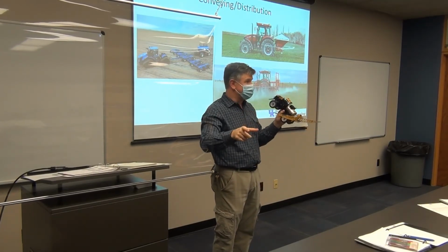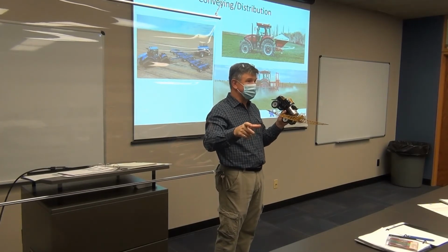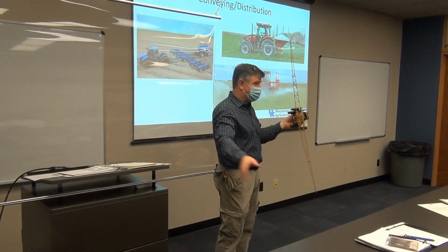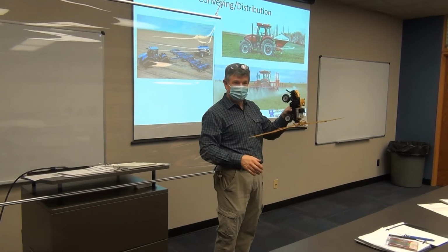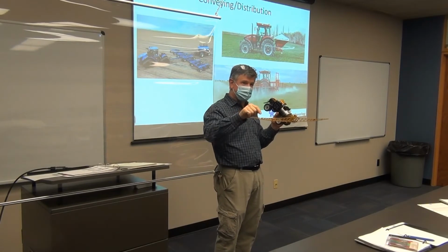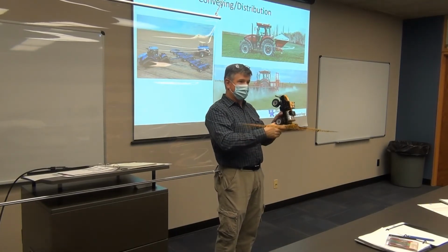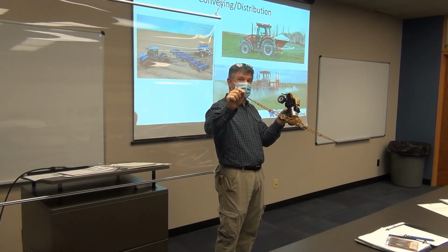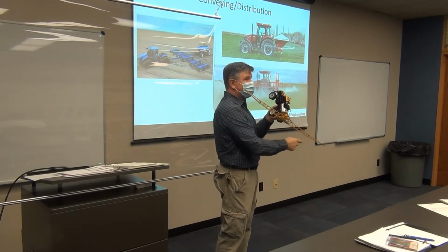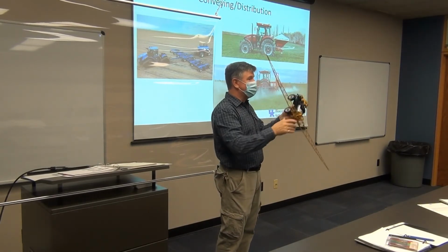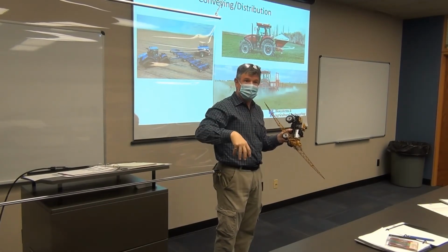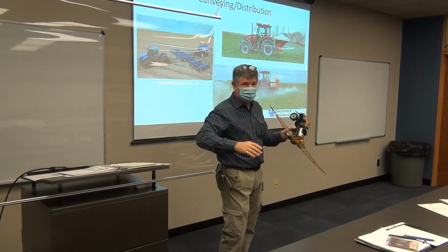What's that doing to my application rate on the ground out here? Wow, it's changing it, right? In fact, when I turn real short, I can actually make this boom go backwards, and I can spray back and forth and double and triple cover stuff as I wiggle around tight corners. But now if I'm injecting the chemical at each one of these nozzles out here, when I start around the corner, I have the ability to say, let's put a little more chemical coming out of this one and not as much chemical coming out of that one down there. And so as I go around the corner, I can have a uniform application rate on the ground. The flow rate is different coming out of them, but what's actually hitting the ground is the right amount of chemical everywhere I need across the back of that boom.